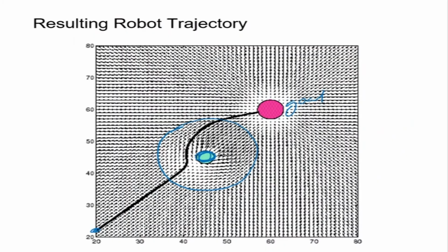Suppose I have my zone of influence here, which is my Q star, and the robot is coming towards the goal. It is moving almost in a straight line towards the goal because that is the shortest path. Only when it enters the zone of influence does the repulsive force start pushing the robot away, not before that. From here, the robot is getting pushed away. It goes like this, like this, and goes to the goal.